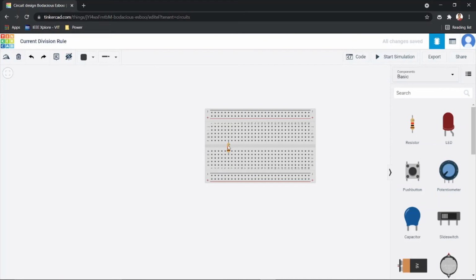And I've just inserted my resistor here. So one end at my F and the other end just connected to D. Then I pick up another resistor and place it somewhere here. Since they are parallel, I'm just placing it here. Okay, so now we need to set the resistance value. Just click on that the same way. You can even name it here as R1, which is 10 kilo ohm. Sorry. And then we have R2. Just click on that. It's going to be R2 and that is 5 kilo ohm. Fine. And then we need a power supply.